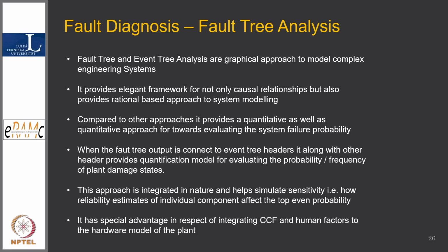We can develop the rules using this fault tree analysis, and we can develop an expert system, machine learning algorithm for fault diagnosis, not only for fault diagnosis but also for what action to be taken. So it is called precursor, or antecedent, and reaction. So those kind of things we have. And fault trees have some features. It's not only hardware components.